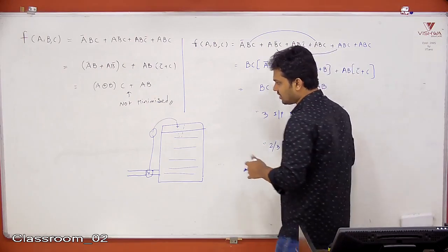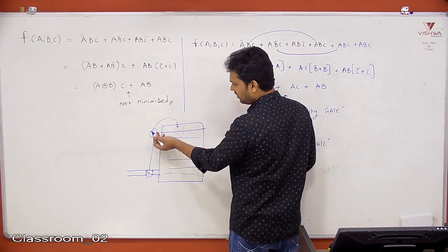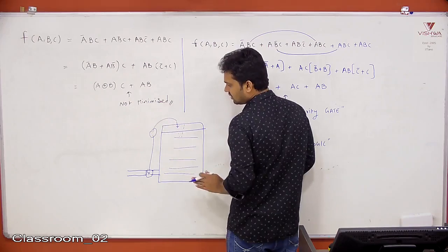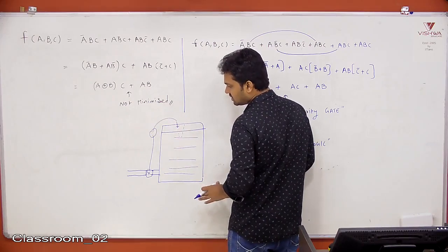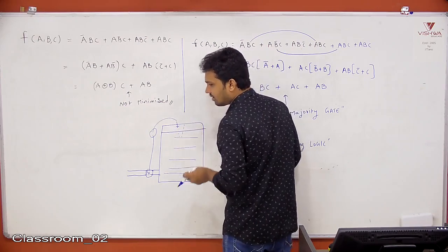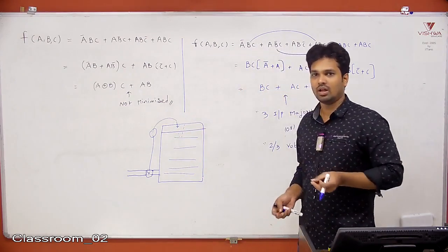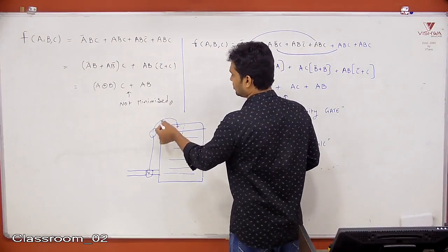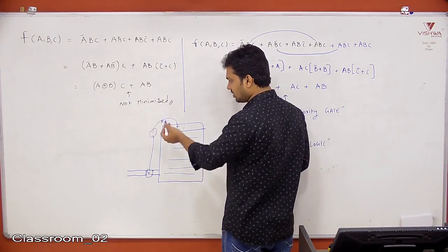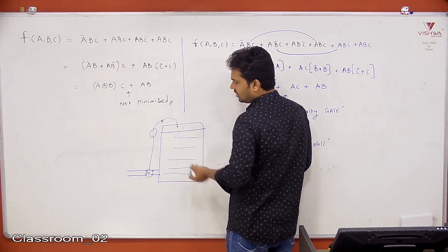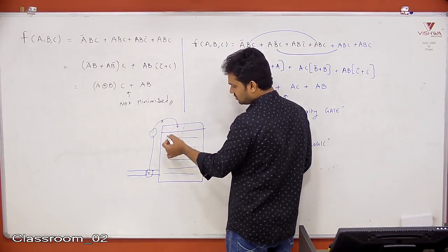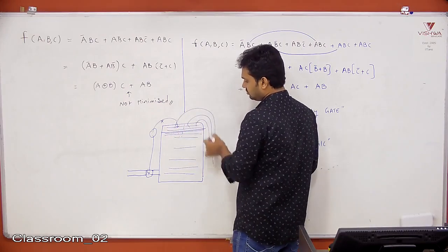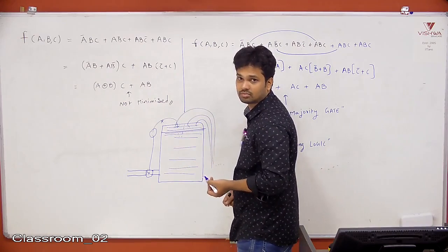For example, whatever you have taken, very good device, very best in the market, level switch and all, the transducers, everything is best. But every device will be having some certain age limit, or due to some environmental conditions it has gone faulty. Out of the 1,000, one may go fault, but that one is with you. If it is not working, what happens? This flow comes, overflow. It may damage your whole system.